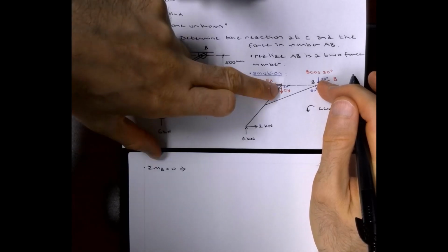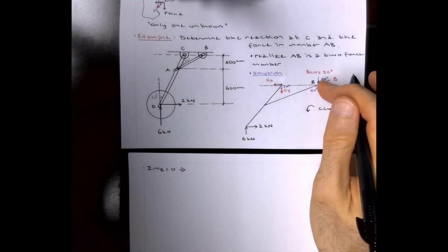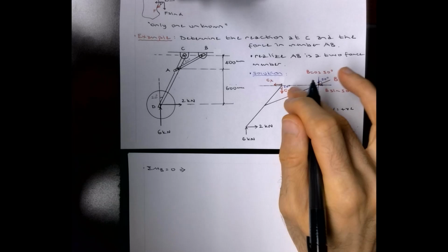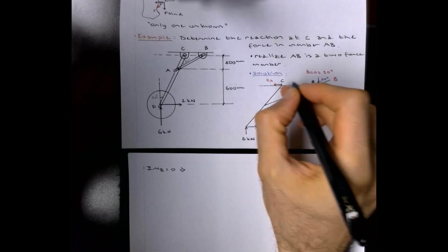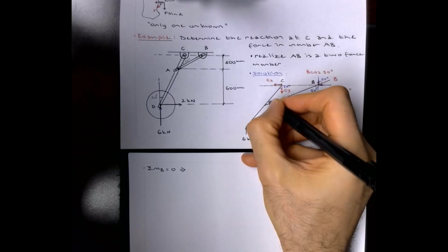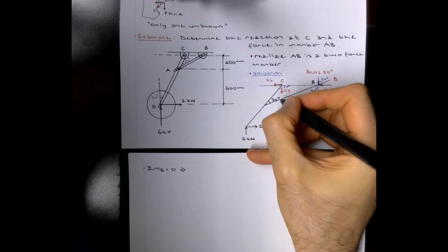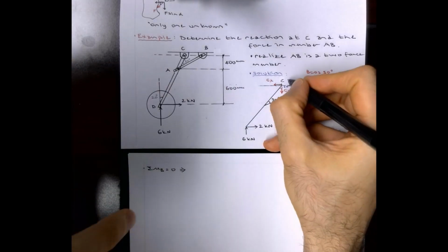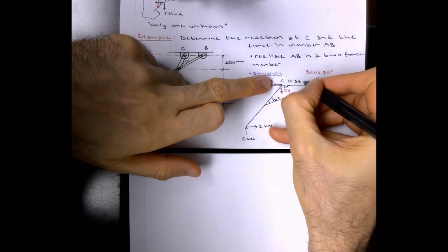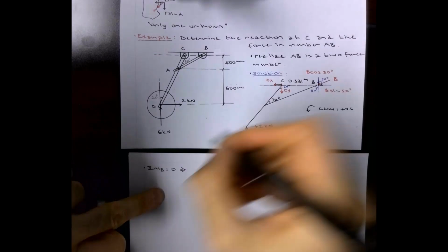So in terms of the distance, I'm feeling something is in terms of dimension. Are we missing any dimension? Let me just look into that, because you need the distance between C and B, right? So you need that distance. We know this angle, which is 30 degree. Distance between C and B is calculated using trigonometry as 0.331 meters. So that is the distance which I'm going to use.